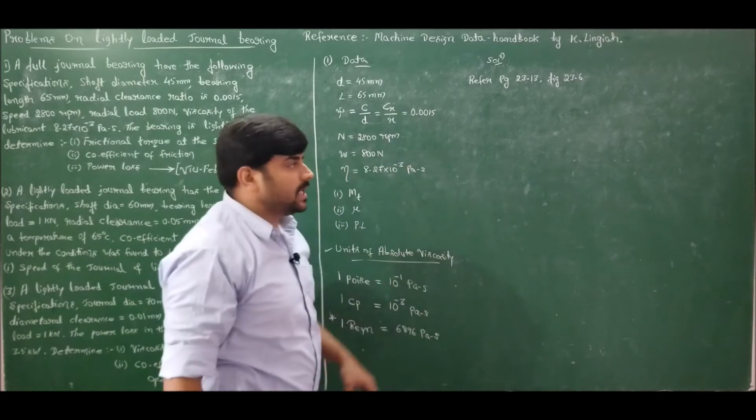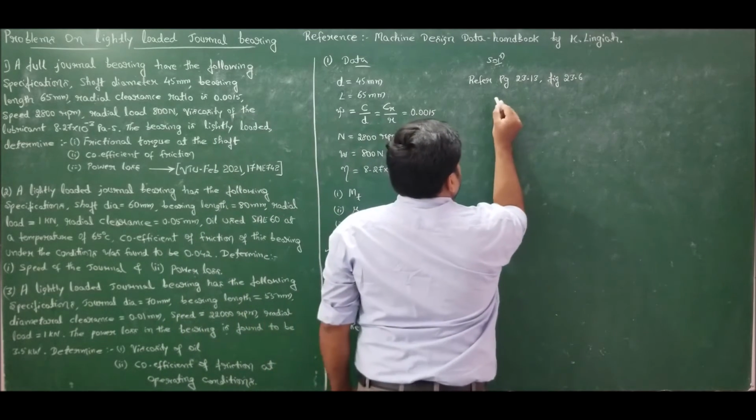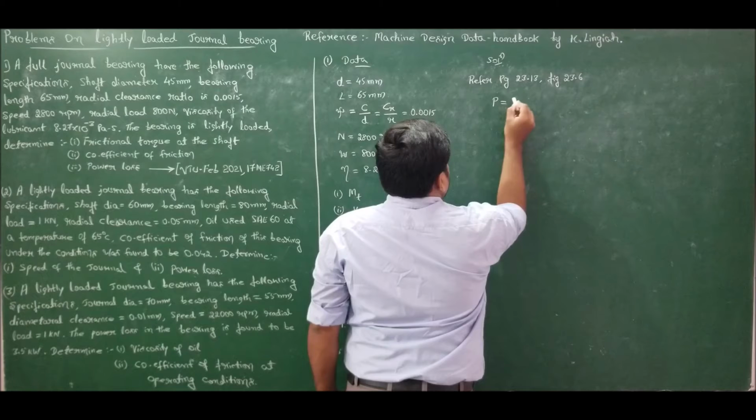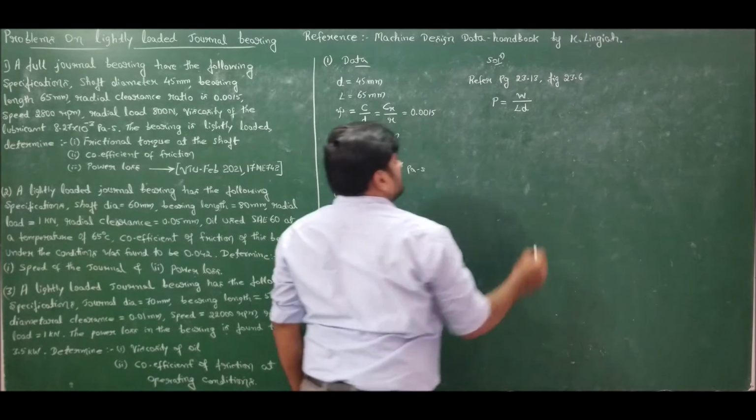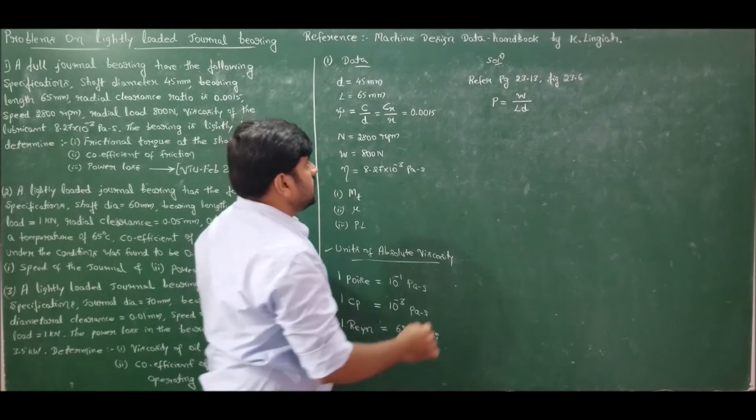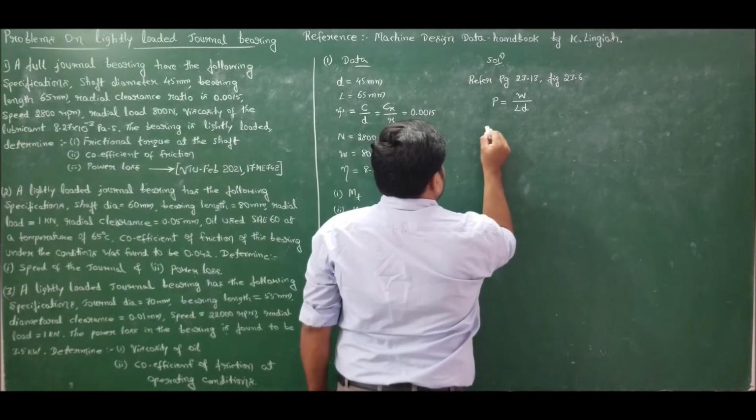You can see the projected area, where you can clearly observe that pressure is given by load divided by projected area, L into D.